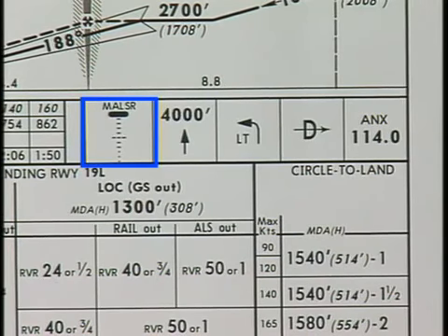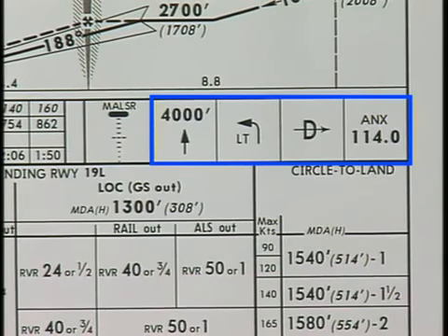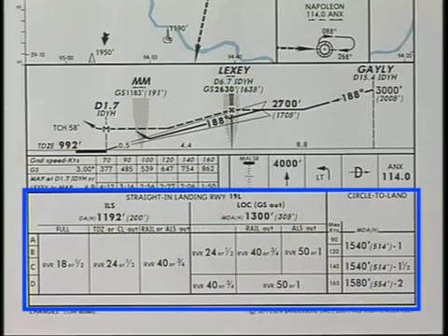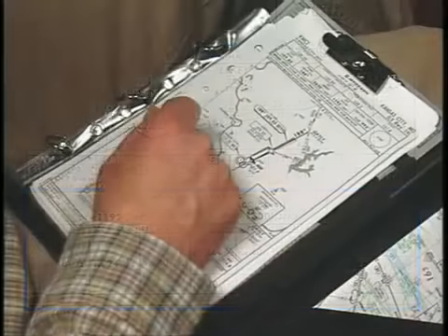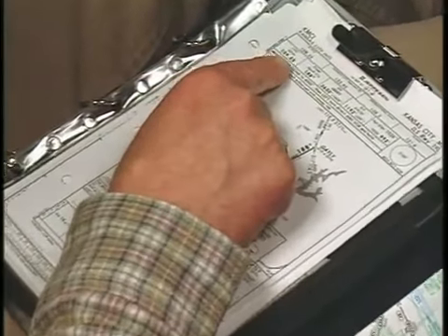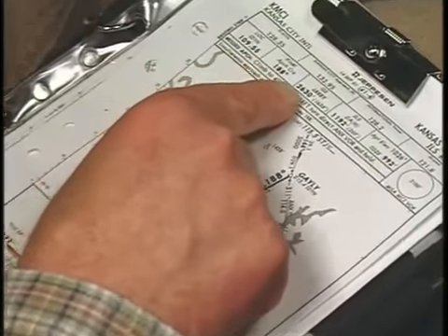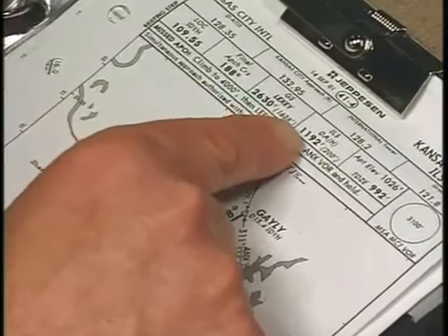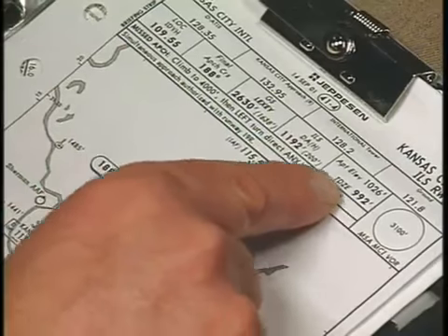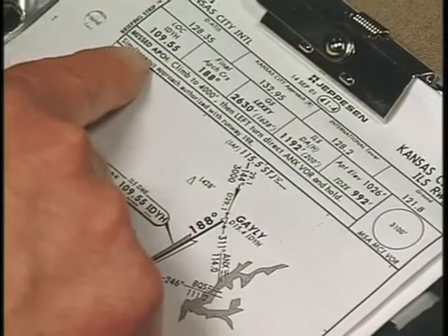In this section, review the approach lighting so you know what to expect when you see the runway environment. Should a missed approach become necessary, this portion of the chart provides a quick reference to the initial up and out maneuver. Finally, review the minimum section to determine the minimum altitude and visibility for the approach. The pre-flight and in-flight review of the approach helps to reduce your workload during the actual approach. It also reinforces where to find the information quickly if needed.